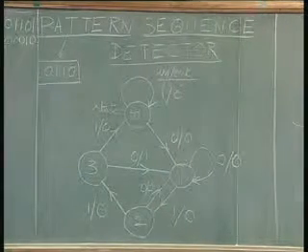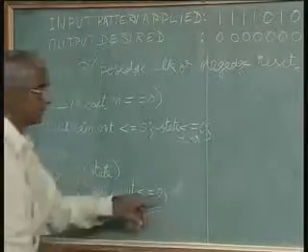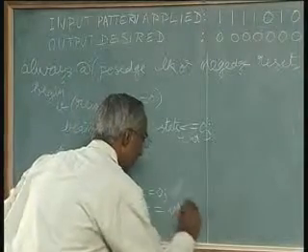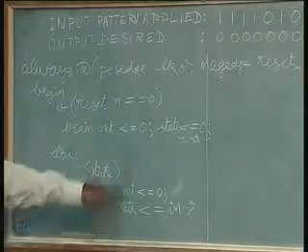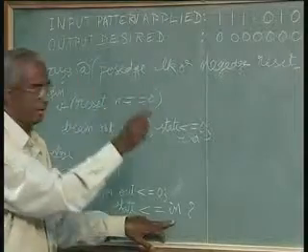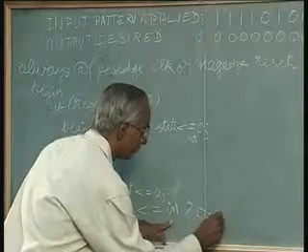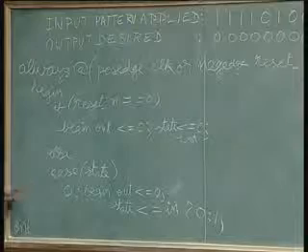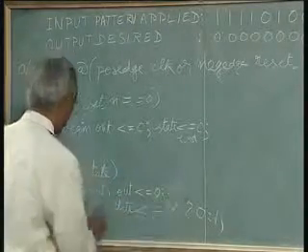So this is once again a case for using a mux. What is the selector pin here? That is nothing but in. So we will put in, then a question mark. Now it's a very simple thing. If it is 1, it has to remain in the same state. So what we just put is 0 here, then colon and then 1. It's quite simple like this. Are we clear? Now let us try in the same fashion here, and there must be one end.